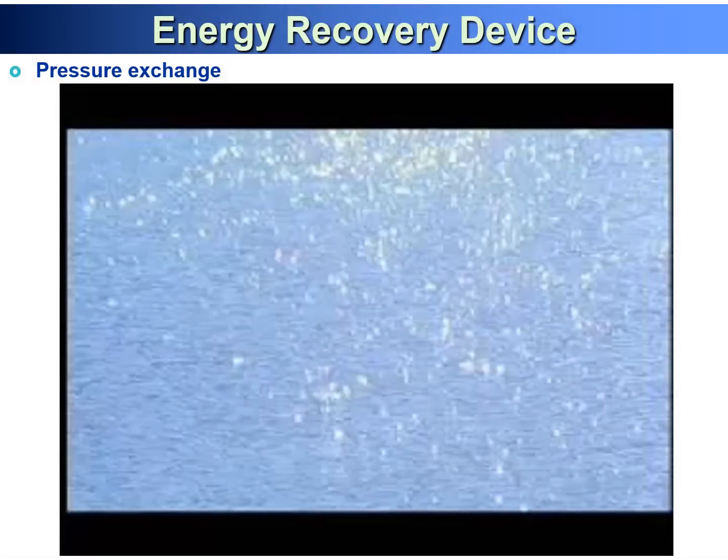Let's watch the video on energy recovery device. The pressure exchange is one of the breakthroughs of the seawater desalination in RO process. So this really reduced a lot of energy. That's the reason why the RO membrane process is a dominant technology for our seawater desalination. So this is the example of post desalination plant to apply for pressure exchange energy recovery device.